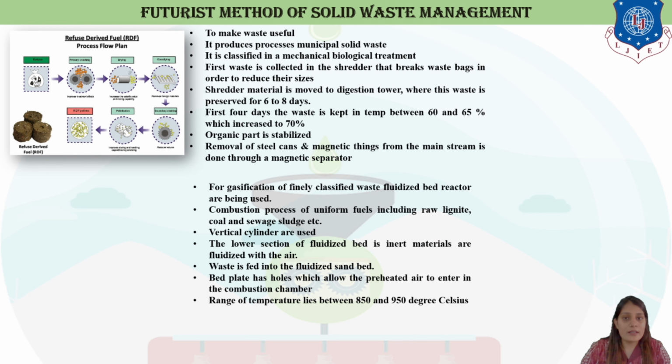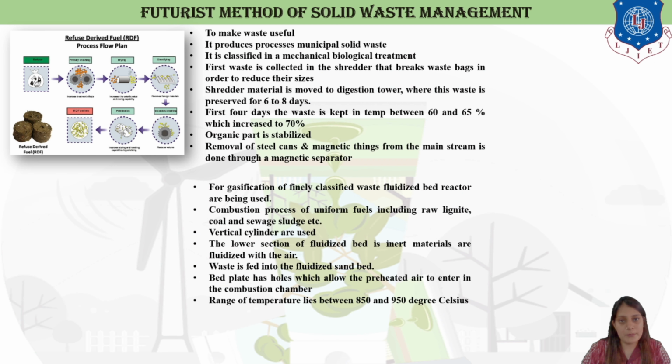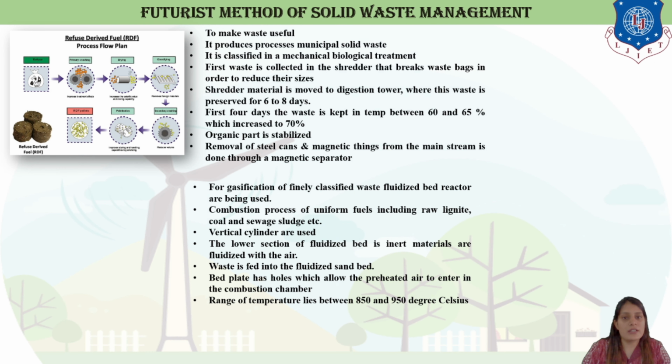For the first 4 days, the waste is kept at a temperature between 60 to 65 degrees, which is increased to 70. So we keep it according to the temperature. We see how the properties change according to the material, and what changes take place. So basically it is classified as mechanical biological treatment. And lastly, we get some organic matter which we can use. We also remove steel cans which are not required in the material process. So this is refuse-derived fuel, the futuristic method for solid waste management.